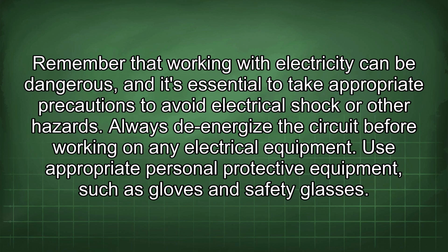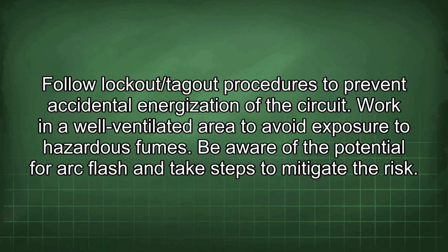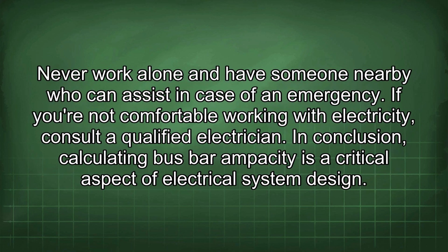Use appropriate personal protective equipment such as gloves and safety glasses. Follow lockout/tagout procedures to prevent accidental energization of the circuit. Work in a well-ventilated area to avoid exposure to hazardous fumes. Be aware of the potential for arc flash and take steps to mitigate the risk. Never work alone and have someone nearby who can assist in case of an emergency. If you're not comfortable working with electricity, consult a qualified electrician.